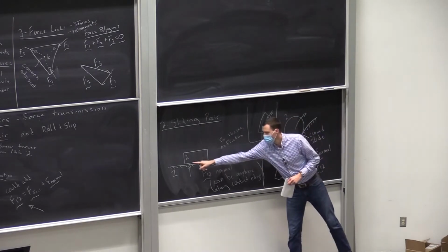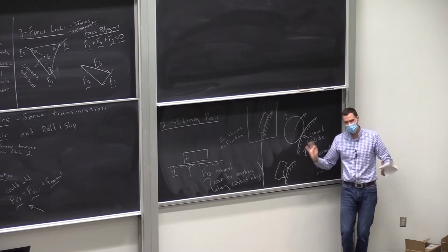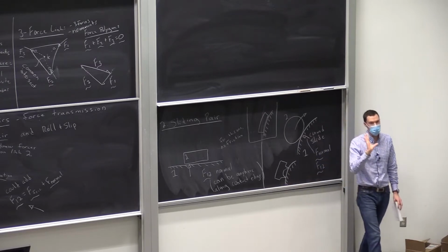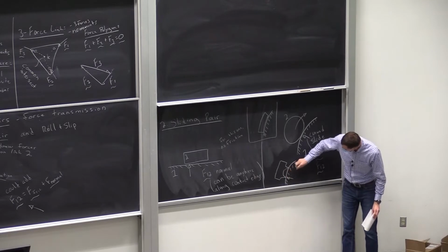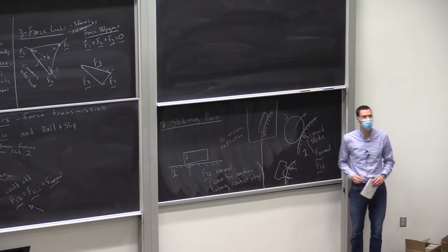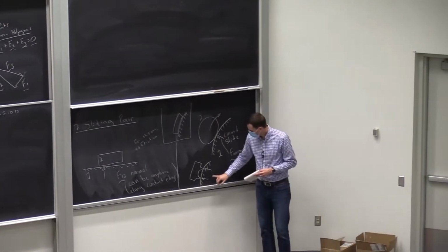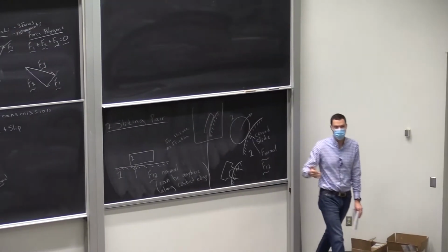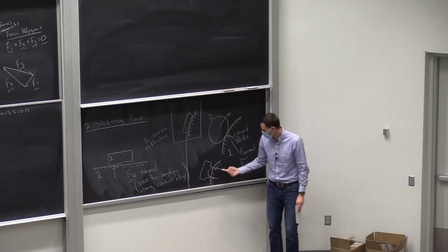This one, perpendicular to the slide, but you don't know the location. It's kind of like it could be anywhere along there. So in reality, this one's a little bit unique because there's 2 contacts. So maybe the most accurate way of doing this one is you'd say there's actually 2. They're both contacting. So what's really happening is there's a force here and a force here. What you could do is replace these by an equivalent single force. So that's a trick that we'll look at later. You could replace these 2 by a single force.